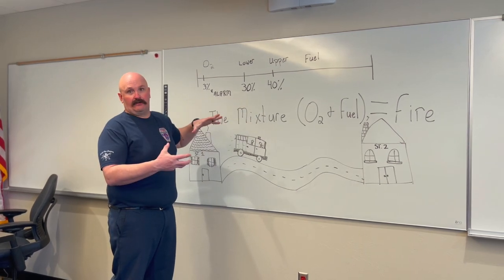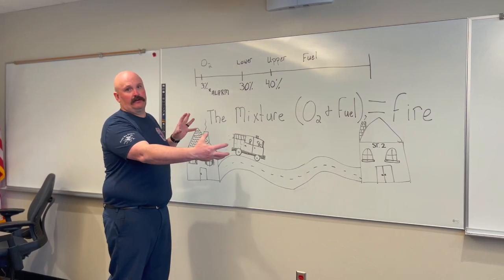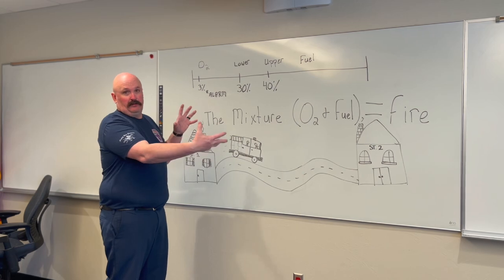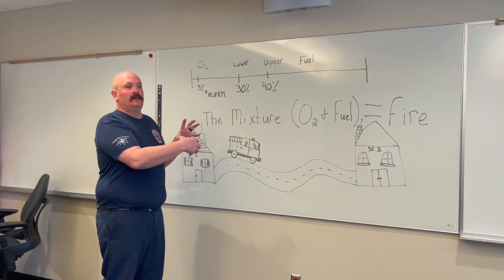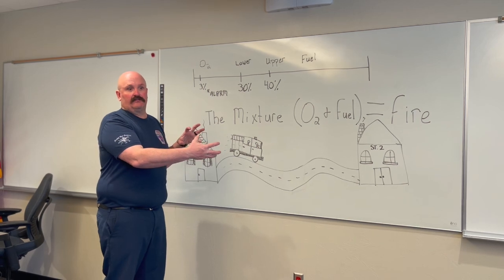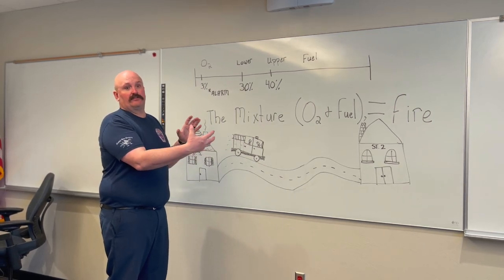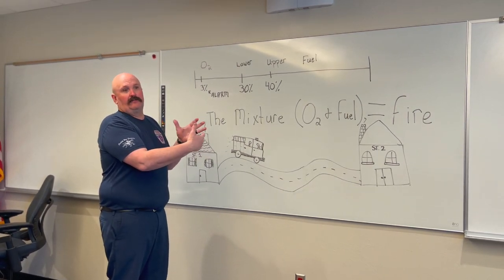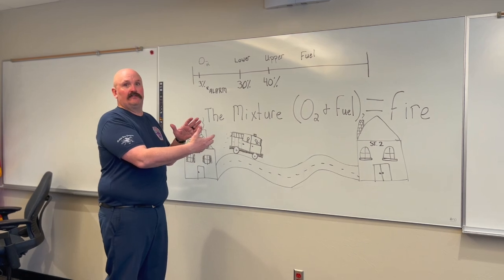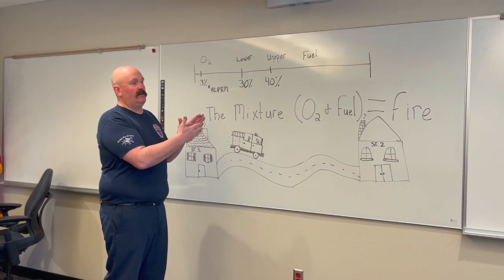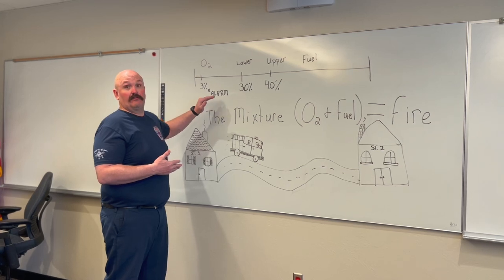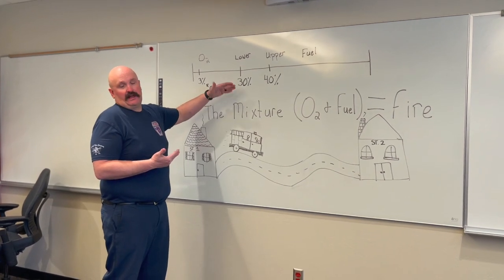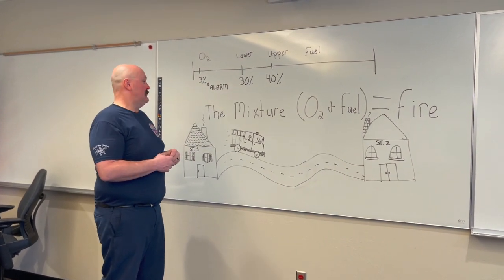That protects us from a wide range of chemicals and flammable products, regardless of their correction factor. So we don't need to know the correction factors, we just understand that there are various flammable products and a wide range of those. In order to protect ourselves, the CGI will alarm at 10% towards what our calibrated gas is.